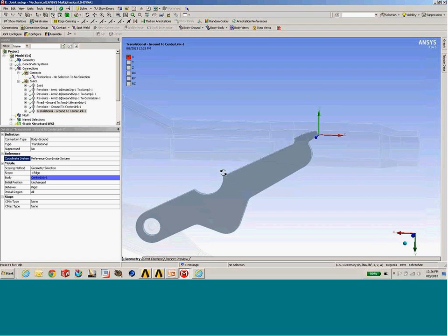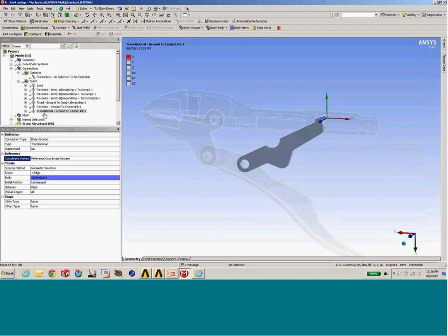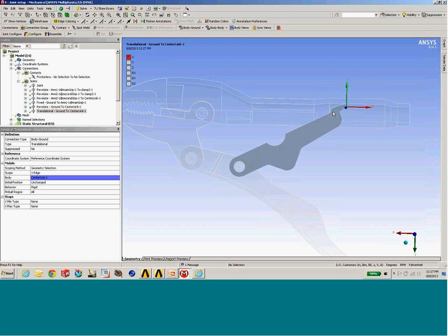And so again, we could check that configuration once again. We could use the configure tool. We can grab right on that translational degree of freedom and make sure that's all making sense. That looks good. But now, in addition to this, let's say we were going to model a situation where there might be a gap between the set screw on the end of this plier and that link, because that link basically has to pivot on the end of the set screw in order for the jaw to be able to close.